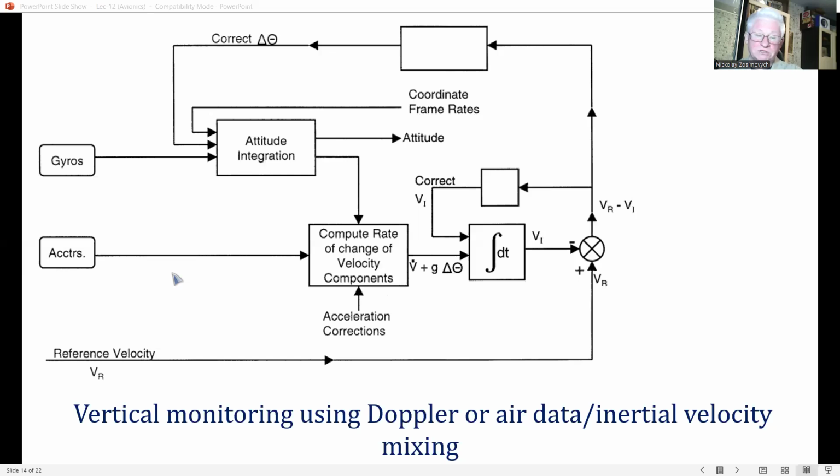The major source of error in the initially derived velocity component arises from the vertical error or tilt error in the AHRS, producing gravitational acceleration errors which are integrated with time.